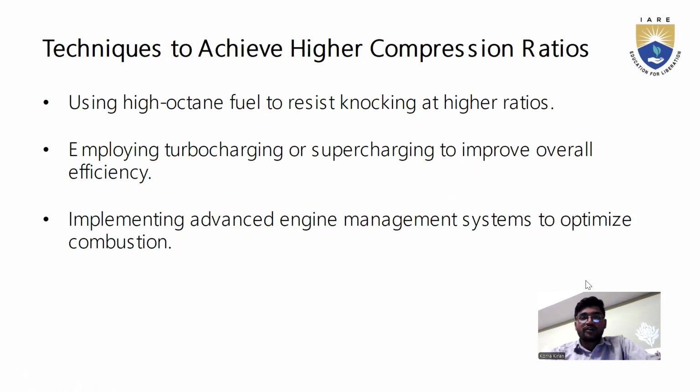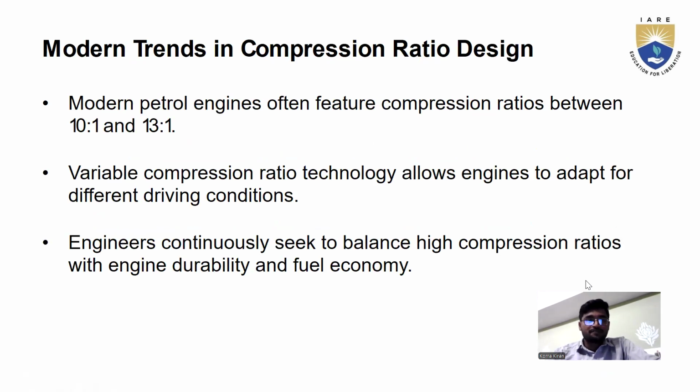Techniques to achieve higher compression ratios: using high octane fuel to restrict knocking at higher ratios, employing turbocharging or supercharging to improve the overall efficiency, and implementing advanced engine management systems to optimize the combustion.